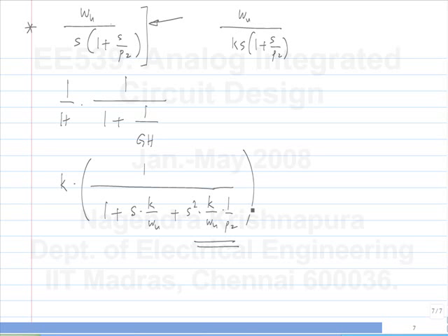Like, how do you make any judgment on whether this is a good thing or a bad thing, or what really happens in the time domain? So you can calculate the damping factor or quality factor to see what happens to the step response. What was the step response of the closed loop system before? That is, without P2, what's the unit step response of the closed loop system? Of the closed loop system.